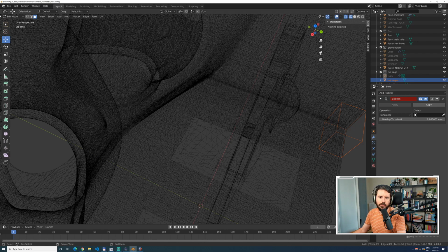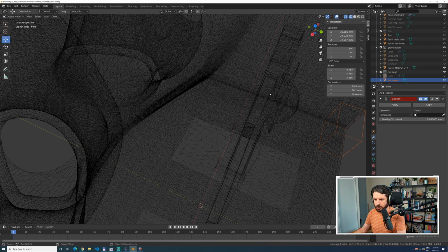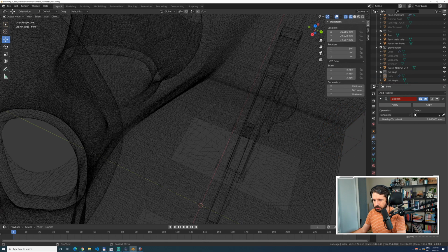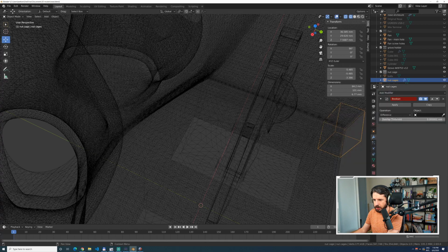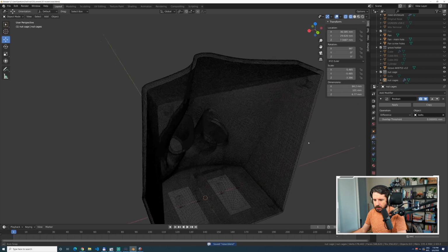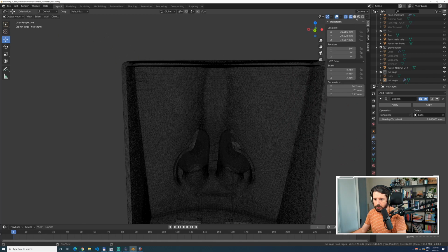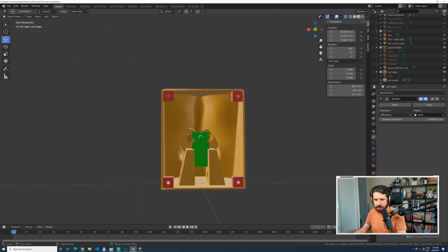I'm in the wrong view, that's why. Need to be in object mode. So we are. Yeah, we shouldn't be on the bolts. This is wrong. We should be on the net cage, adding a Boolean difference with the bolts. Yes, yes. All right, and so yeah, we have holes in all our bolt cages.